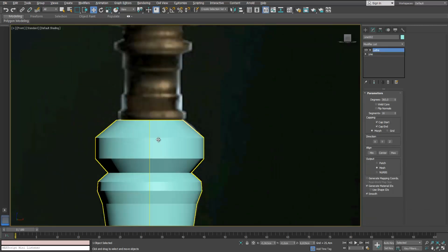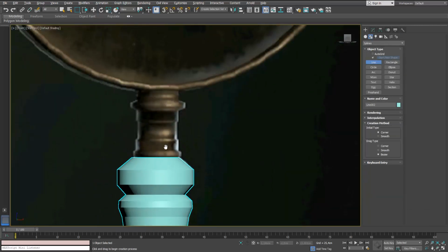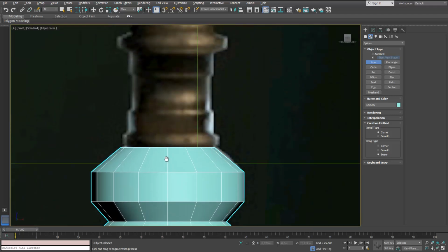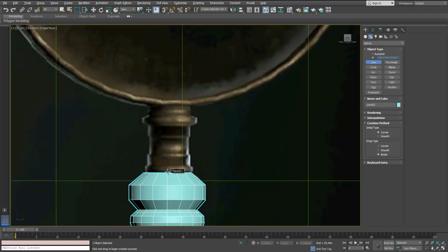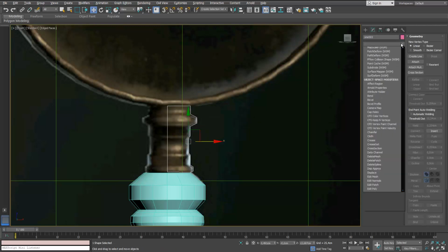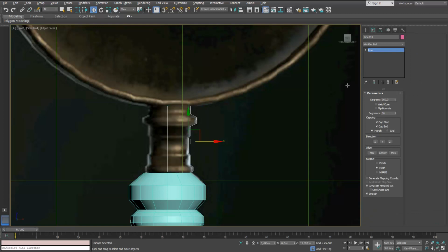This is actually a quick way to create 3D shapes and 3D elements if we have cases like these, where we have something that looks cylindrical and has some shapes and details that we have to cover, and this method will come very handy in these situations. Okay, we're gonna do the same thing when we are done with that shape. We're gonna close that line and apply the lathe modifier.